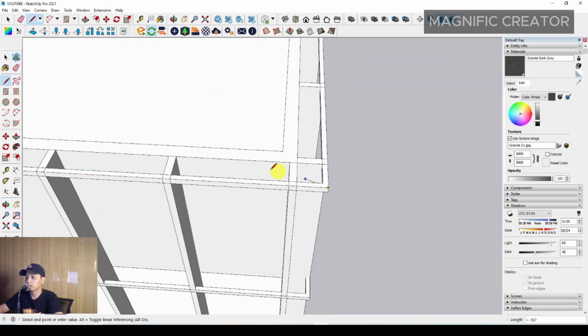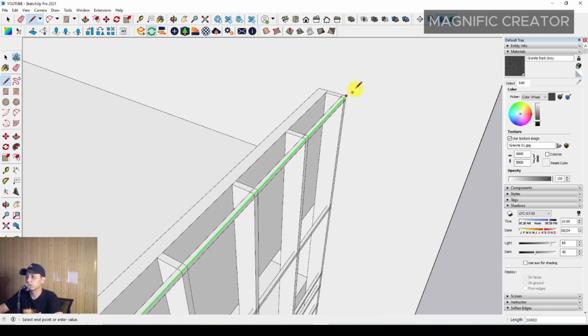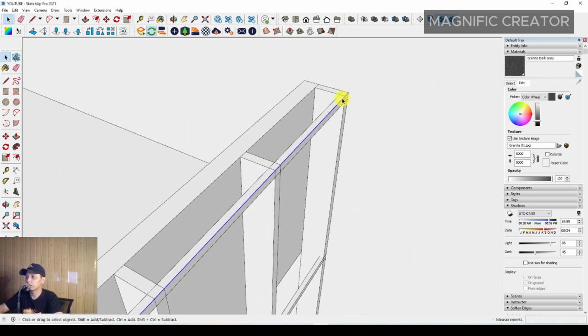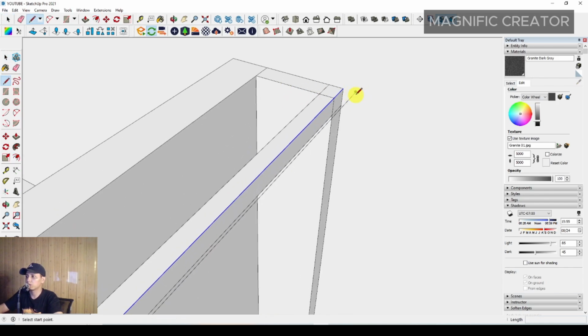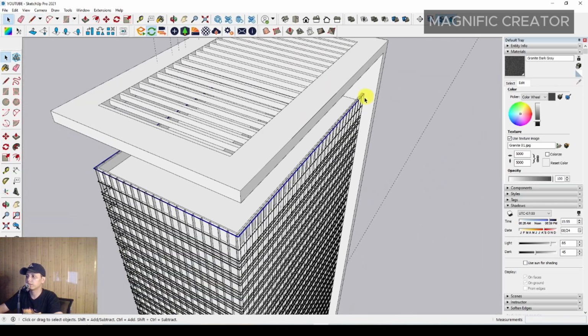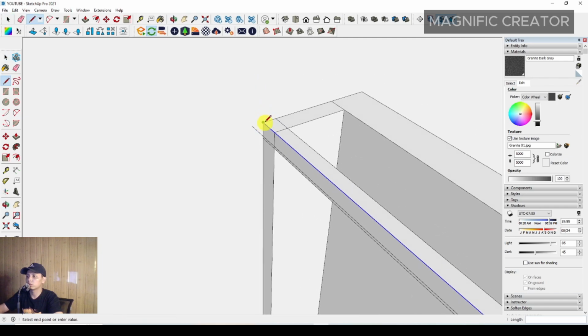We can adjust with the 3 positions over there. Then we have to triple click and offset it outside. You can offset it outside around 60 millimeter, for example, because it is double or triple glass anyway. So it should be a thick glazing.